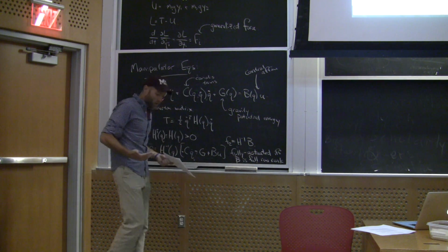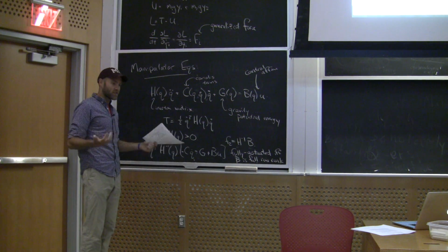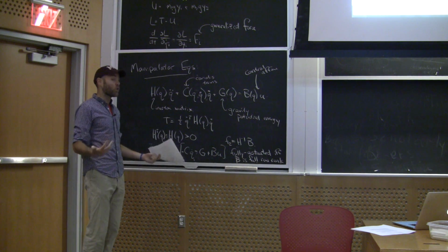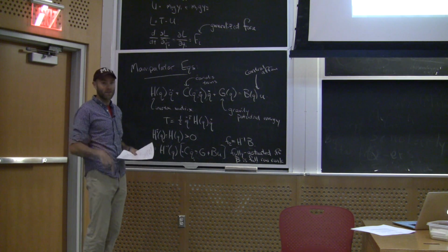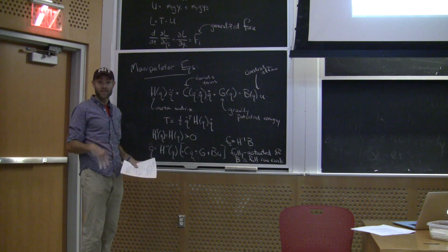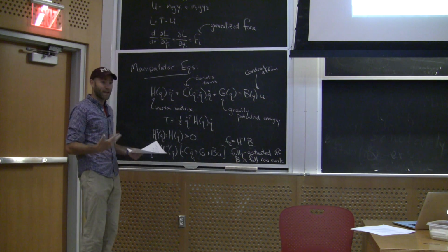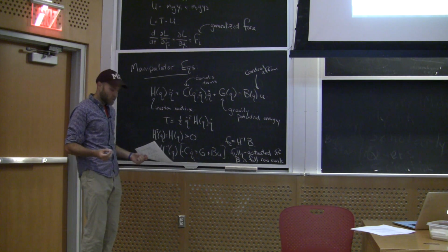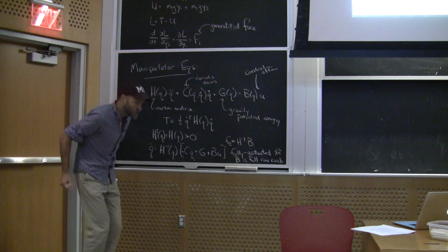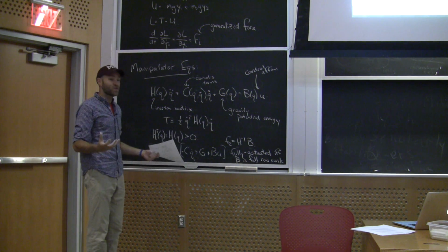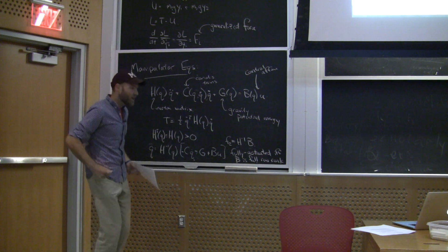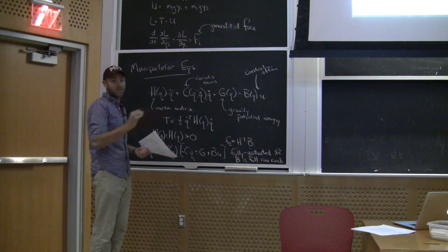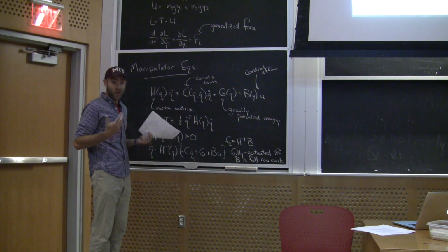Okay, why do I need that? Basically, I'm a big complicated system. I've got lots of actuators. Depending on how you count them, I maybe even have more actuators than I have joints, right? Because I've got multiple muscles that span multiple joints and things like this. So I might actually have more actuators than degrees of freedom. But it depends on what level you model. But somehow, when I jump, and let's neglect aerodynamics for a second, when I'm flying through the air, nothing I do with my muscles is going to change the trajectory of my center of mass, right? My system is underactuated.